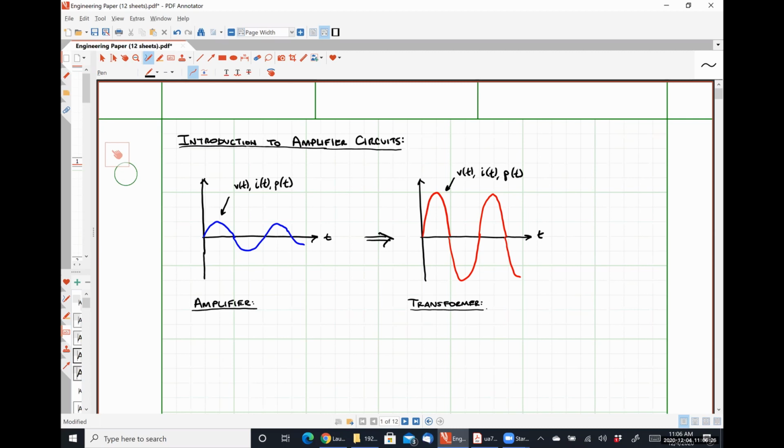When we send voltages over long distances, we use very, very high voltages, because in a transformer, if you step the voltage up, the current goes down. So if you transmit a very, very high voltage, you're transmitting a very, very small amount of current. And when you have a small amount of current, the resistive losses in the lines are smaller as well. So it makes economical sense to send high voltage signals over large distances. And that's something that we'll circle back around to more at the end of the class.